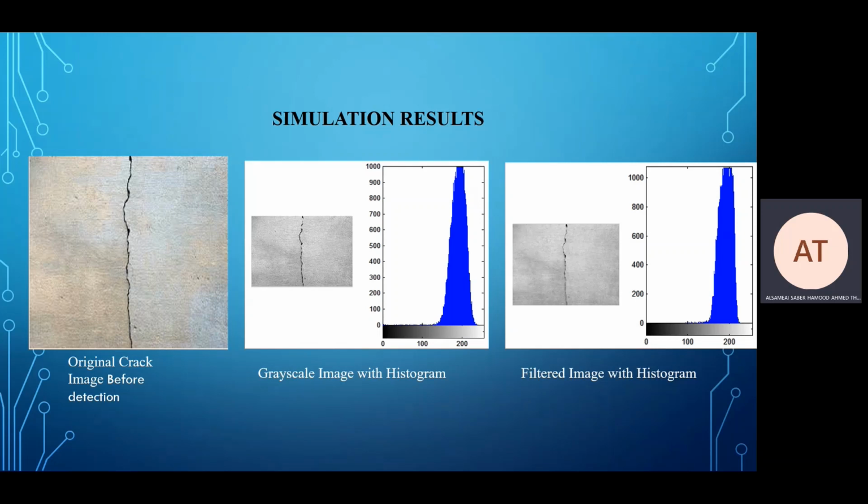From the histogram, it can be observed most of the image grayscale colors are between 150 to 255, and very minimal colors are from the range 0 to 150. And therefore, it indicates that most of the crack pixels are between the 0 to 150 range, and those that form the background range between 150 to 255.